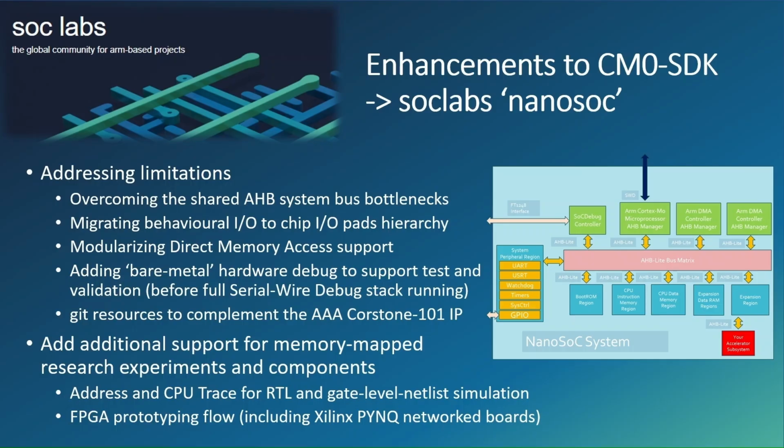One of the issues with the CMSDK is it has a single manager, multiple subordinate bus system. So we've tried to overcome some of the bottlenecks in the bus architecture. We've taken it from a subsystem to a full SoC implementation at the pad level. We've added in DMA support for multiple DMAs, up to two instantiations and different DMAs, as well as adding in our SoC debug controller.